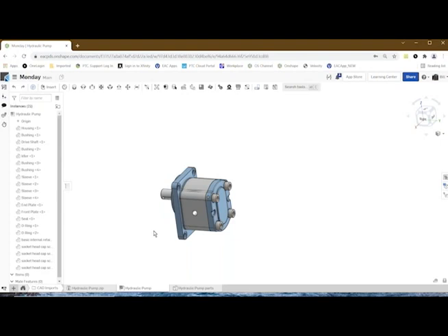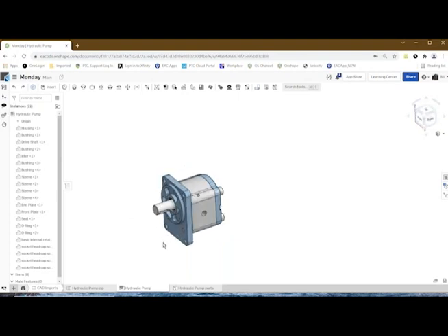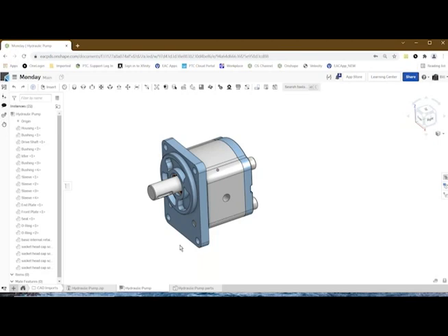If this was a much larger assembly that had sub-assemblies and all that, each sub-assembly would get its own tab, and then there'd be a top-level assembly tab that brings all of those in. So that's what I meant by keeping the integrity of the way that the assembly was put together, keeping all the sub-assemblies separate, and then also having that top level that includes everybody. So that's really the preferred method. Certainly for large assemblies, that's probably the best way of doing things. So that's a little bit about importing in and working with Onshape.